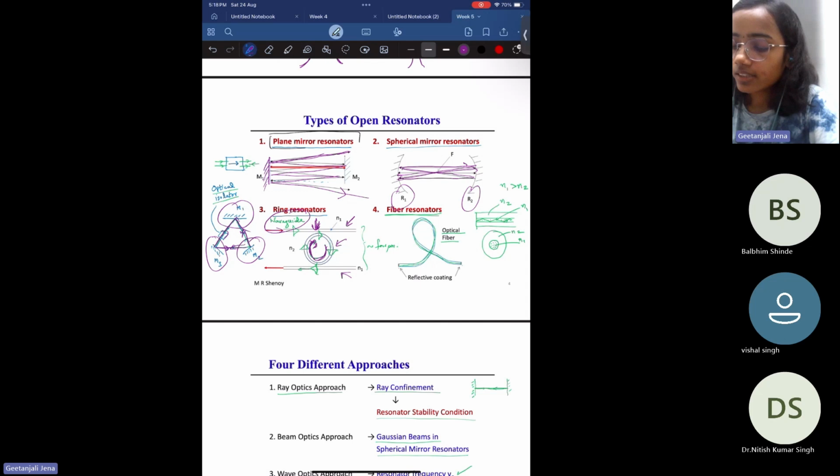It will oscillate inside this ring resonator, and in each oscillation, what will happen? Some power will again couple to this waveguide, and we will get a non-zero power in this input port of this second waveguide. Okay, so in this way, you can use a waveguide and ring resonator system to confine power or to oscillate the power over time.